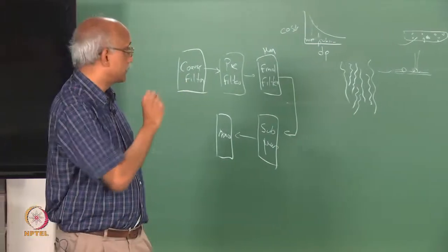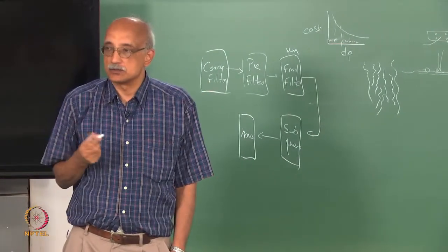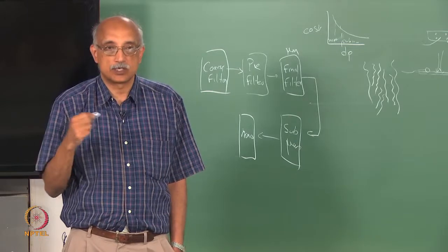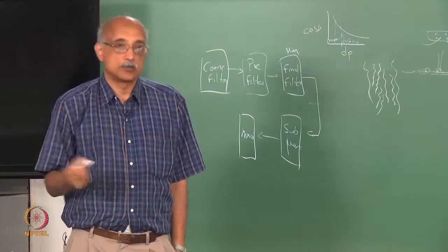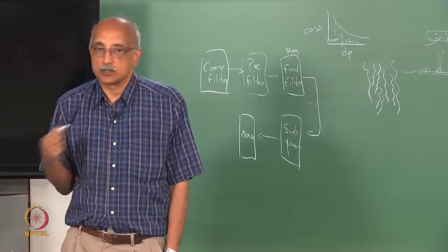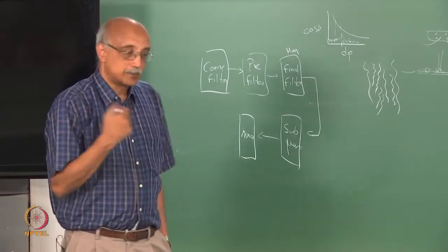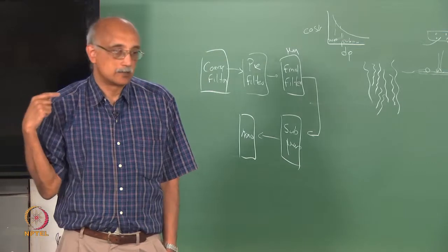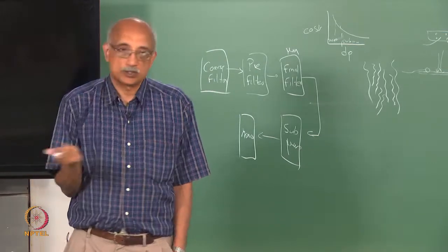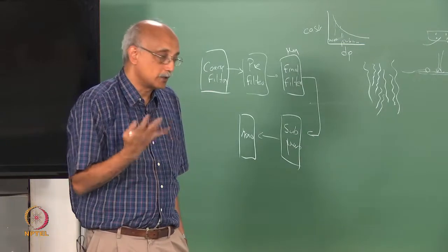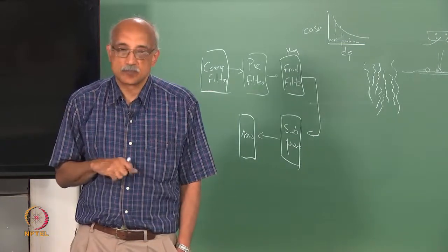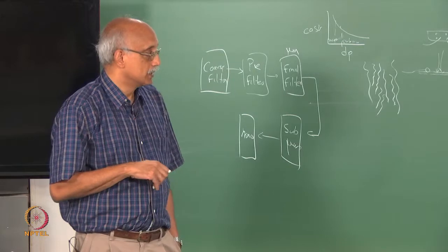So, you have to be, and also your capacity will keep decreasing. The amount of fluid that you can pass through a nano filter is going to be much smaller than the amount of fluid you can process through larger filters. So, there are also pressure drop issues, capacity or throughput issues, and cost issues, which is why nanoparticle synthesis is not a cheap business to get into.